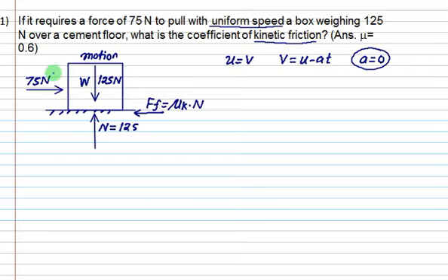So what about the inertia force? Will the inertia force act, or will the inertia force be equal to 0? Inertia force will be equal to 0. So we have a simple balance of sigma Fx, that is 75 is positive, minus mu k into normal reaction 125. So the coefficient of friction is 0.6.